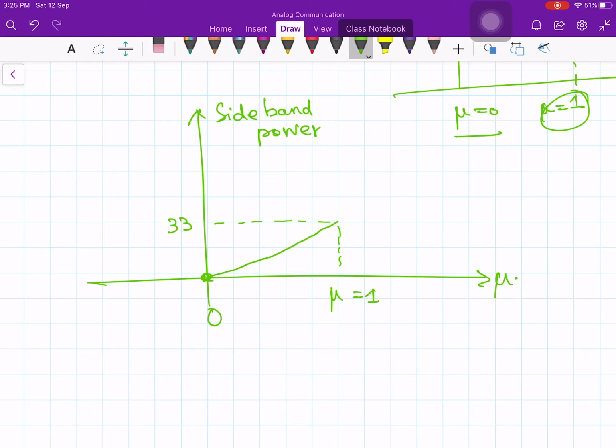Okay. So this discussion we have carried out is valid when the modulating signal was purely a sinusoidal signal. One can prove that for a more general kind of modulating wave, message wave, m of t, the power efficiency can be increased, but under no circumstances will it be more than 50%, like we discussed earlier in one of the lectures. So you cannot achieve more than 50%.